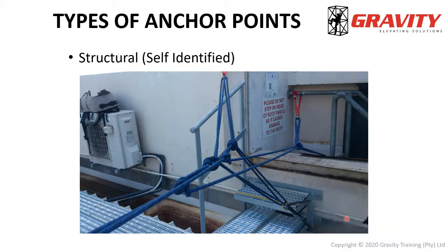So in this image here, you can see the technician has used these railings with slings and carabiners, and there's another one going down there, there's a sling going up there with a carabiner. He slung the foot of the stairs as well, and he's sharing the weight on this line through all these different anchor points.